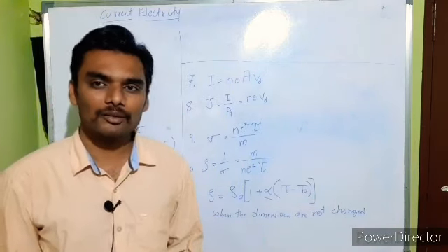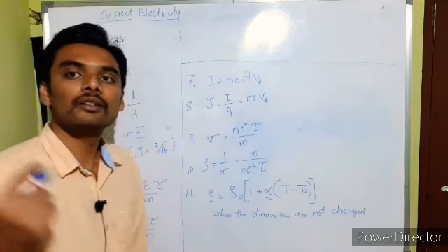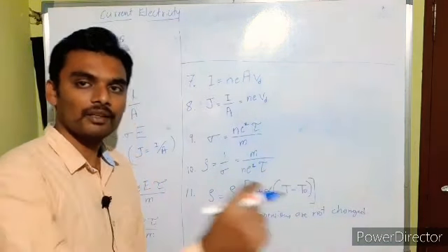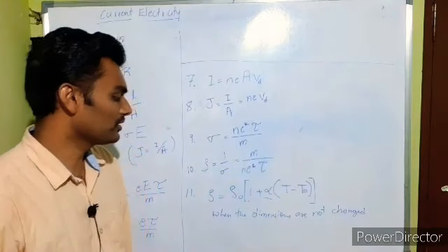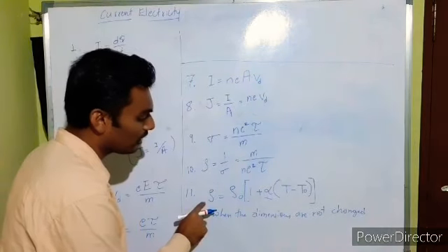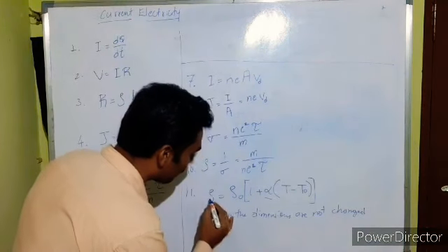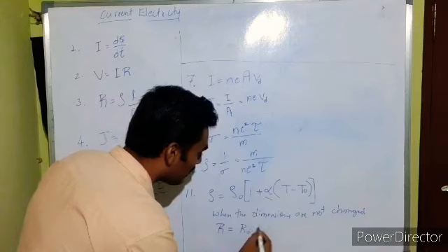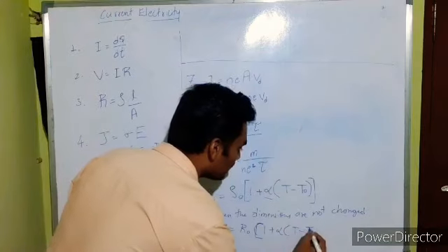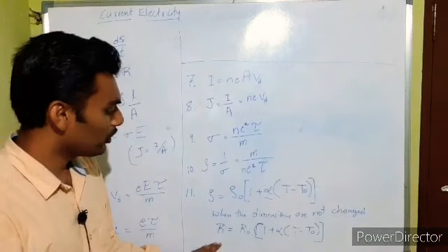Dimensions are not changed. Thermal expansions are all neglected, nothing to worry about, they matter least for us, but the temperature is changed. Area of cross section is not changed, and the length is not changed. That will give us the relation for resistance directly, since the dimensions are not changed. I can write directly, instead of rho, R is equal to R naught of 1 plus alpha into T minus T naught. Okay, so this is again an important formula.